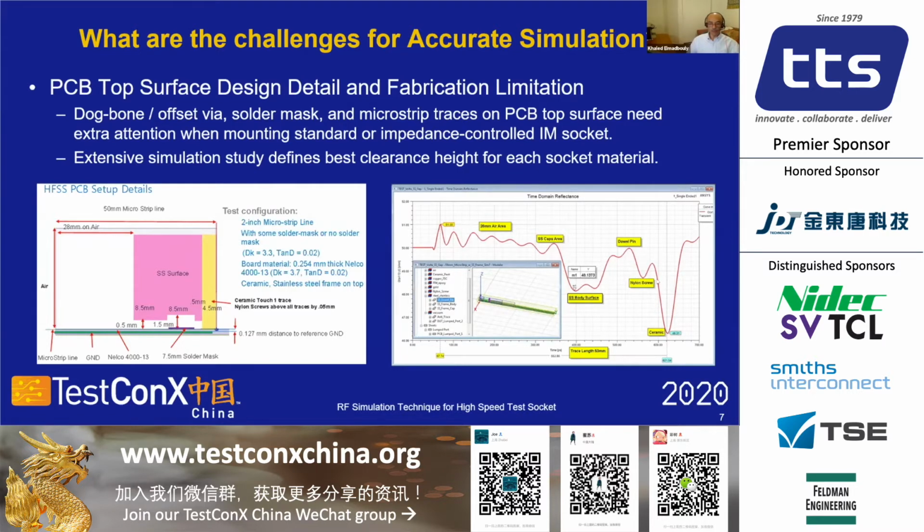Then we have an Allen screw that is almost at the stainless steel level, which also has an impact on the microstrip trace. And when the ceramic or the Vespel material is sitting on top of the PCB, on top of this microstrip trace or the signal pad, you will have about 4 ohm of impedance mismatch because of the material.